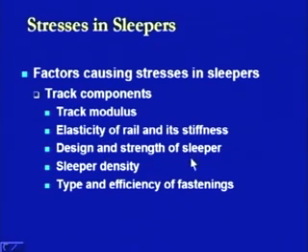Then the design and strength of the sleeper, this is another important aspect. Whether the sleeper is heavier in nature, what is the size of the sleeper, the loads which are coming at that sleeper, whether it is in a position to dissipate those loads or to distribute those loads to a wider area at the bottom, then that sleeper is fine. The sleeper density.